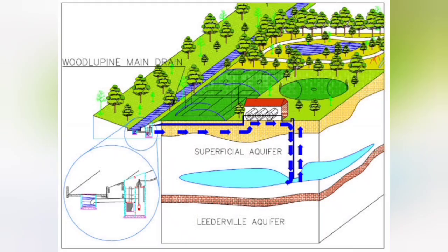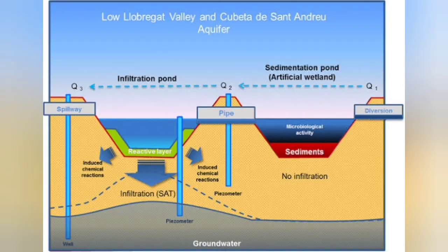So, infiltration of water through the surface takes place generally over small periods of time, and it is the process of redistribution of soil water that goes on for most of the time and therefore predominates. When rainfall ceases, the water that was wetted during the infiltration process starts to drain, with the soil being wetted lower down the profile.